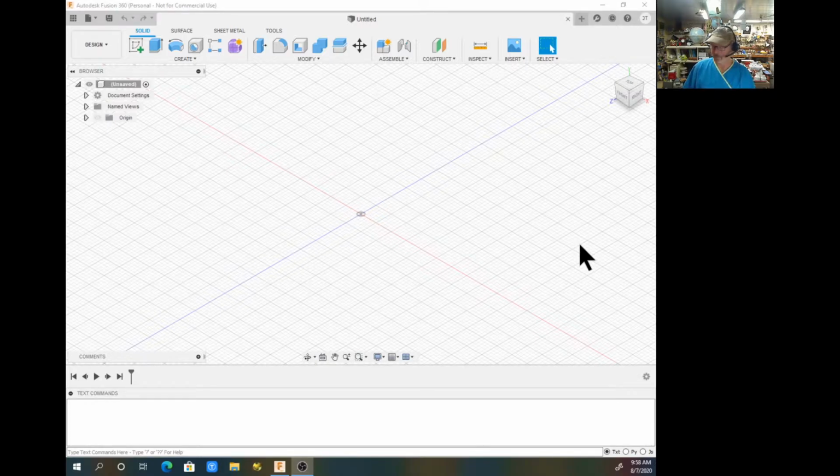It's a real simple one. I kept it simple for one reason: I'm really making these. Now these are two little cutouts I made, and I kept them simple because one of these has been cut with the Maslow post-processor on Fusion 360, and the other one was cut with the GRBL generic post-processor. I want to compare the G-code and also see if there's any difference in performance. Right now I can say there was no difference, with the exception that when I fired up the Maslow one, it stopped immediately and asked, do you want to do a tool change? That was the only difference.